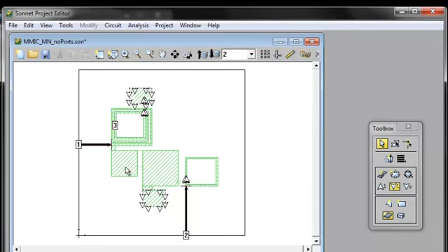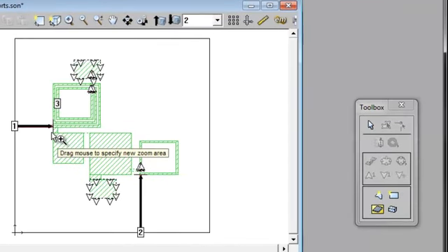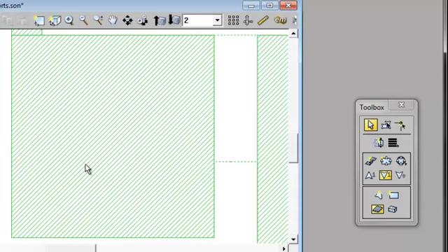Now let's put in a shunt port for the capacitor. Now that's a little bit different. That actually involves first creating a via in the middle of this capacitor, and then assigning that via to becoming a via port, which is sort of like the process of splitting the via and putting a port between them to drive between the two.